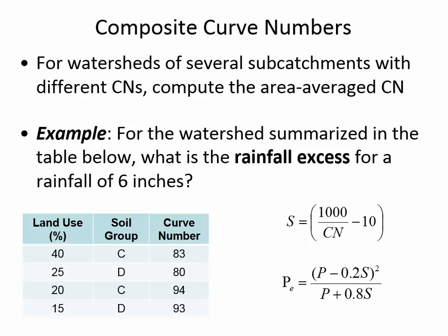But when we are doing WMS, it will usually express the curve numbers to a single tenth place for decimals. So it would say 86.0, since it would round off the 0.95 up. So this is pretty straightforward, and what you have to do manually here will be done automatically when we start performing watershed modeling using WMS.